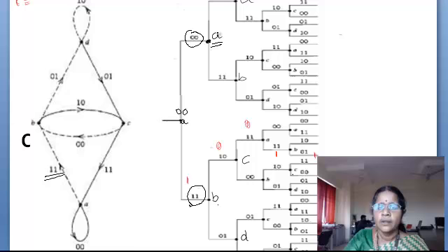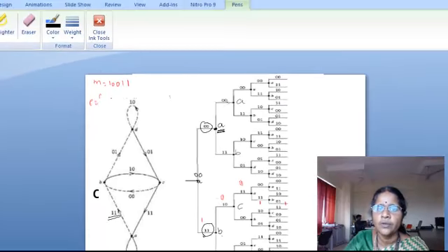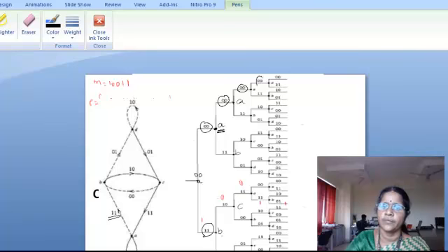Okay, now to travel up in the tree from this point, once again go to state A. If you give an input of 0, then you will remain in the same state, producing an output of 0 0. So you go up. Whenever you are in state A, if you go up, you will be in the same state A, producing an output of 0 0. Similarly, from here also, if you want to travel up in the tree, you will encounter the same state A, producing an output of 0 0. Right. Now from here, let us try to come down in the tree.